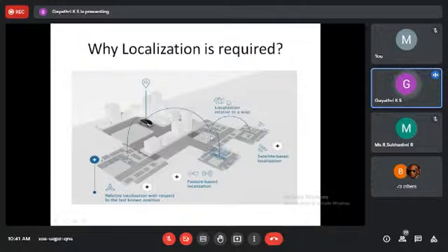The other way of doing this localization is using relative mapping. In the sense, you already have a static map given to you, that is your HD map. You can find out how far I am from this particular building, how far I am from this particular traffic signal. So I will find out the relative displacement from static objects in the environment to exactly find out my current location. There is a set of algorithms with which you can model the localization using that aspect, or you can use feature-based localization. These are some machine learning techniques which could be used for localization. The other way is I can find out my relative displacement. I know where I was in my previous time period, where my vehicle is in the current time period, and how far I have been displaced depending upon the acceleration. You can find out where exactly I am in the environment.